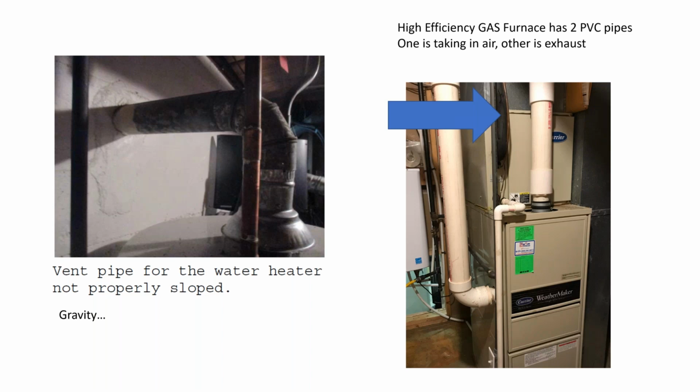Right, exactly. And this is a problem. I'm glad you brought it up because this is vented improperly, and it doesn't look like there's going to be much more room to change the vent on this water heater. This would be the perfect opportunity to switch it out to a tankless water heater, because if you don't get this carbon monoxide out of your house, it can kill you.